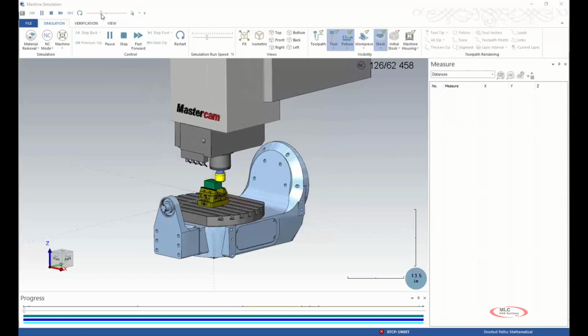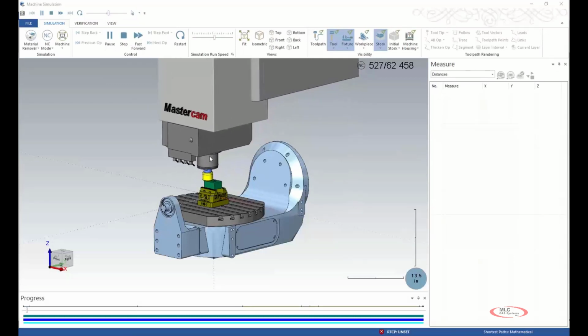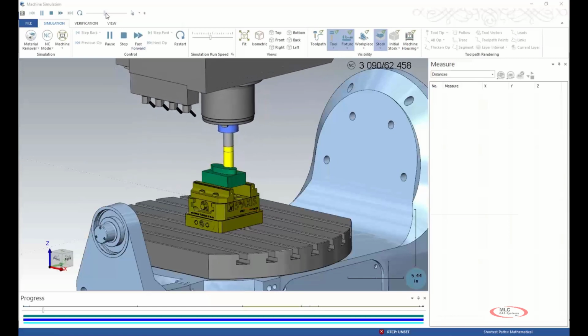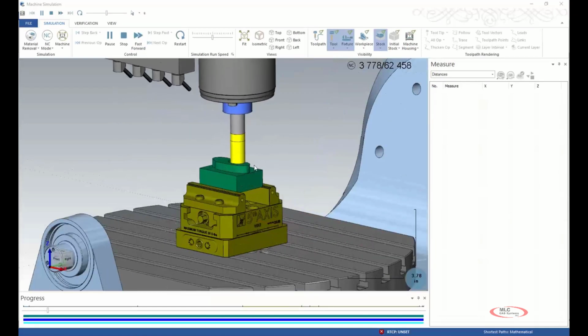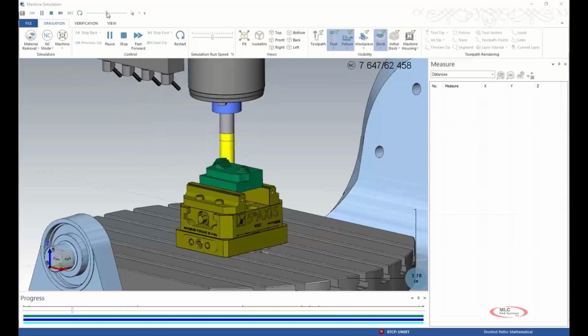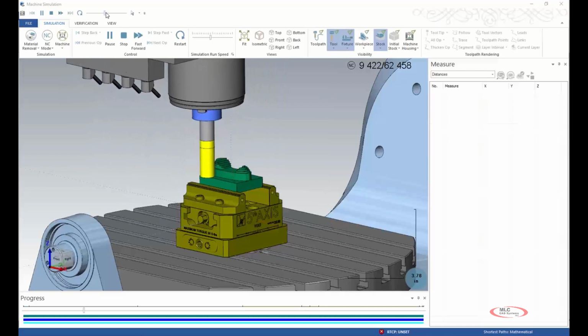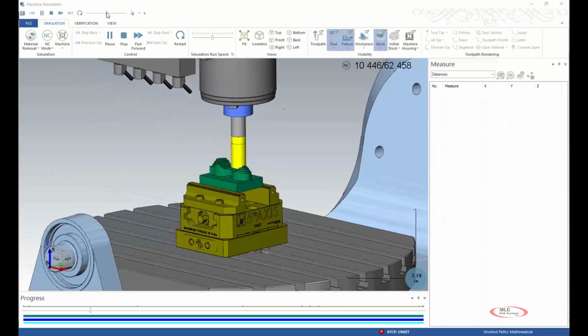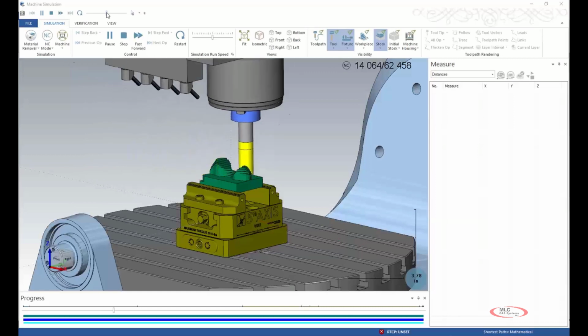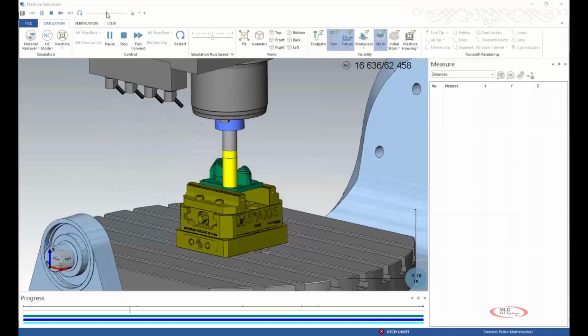We'll go ahead and run this toolpath, and I have my dynamic face milling being done. We'll slow that down a little bit. So here's the example of our OptiRough operation, and again, it's just reading the solid that we have. You see the large step downs with my 10% step over. And then it steps up 100 thou to take care of the profile of the part here.